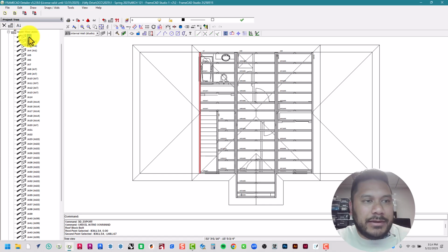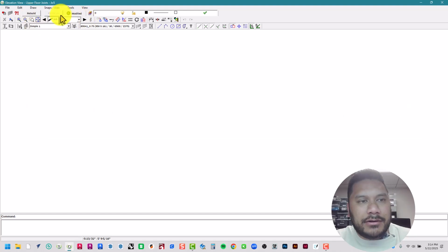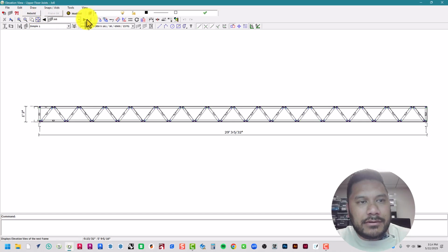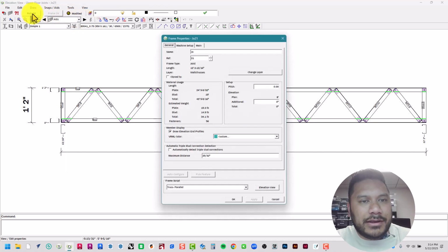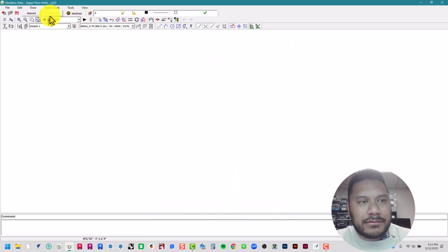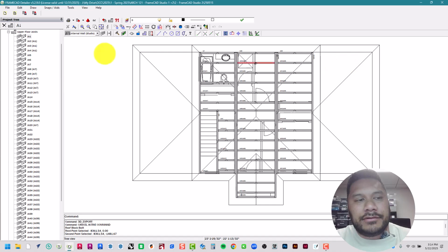Thankfully I don't have that many unique trusses or floor joists because I used a lot of clones. So I think I only have maybe 8 unique ones. 1, 2, 3, 4, 5, 6, 7, 8. So now I can close this window. Everything shows as built. And go File, Export 3D VRML, save it to my desktop, select all, export. And now I'm going to go File, View 3D, 2-story house.